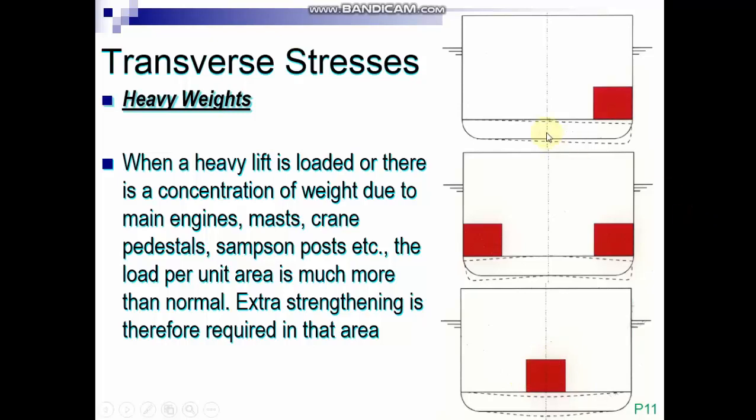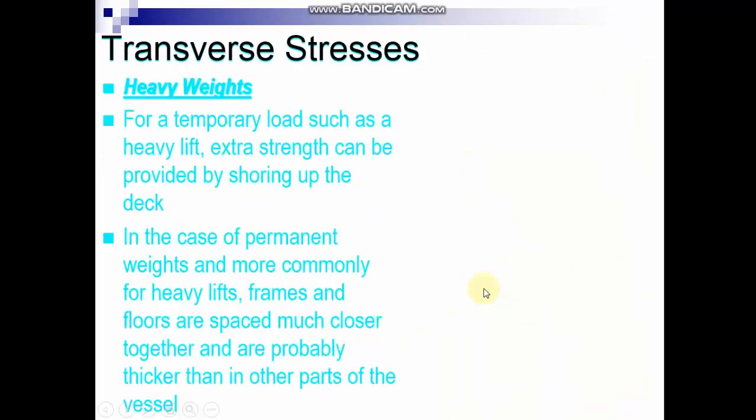As you see, the bottom plating is in stress, and also here two heavy loads on the port side and starboard side are added, and the ship's keel is under stress. This is normally a representation of the main engine, which tends to be installed at the center line of the hull.